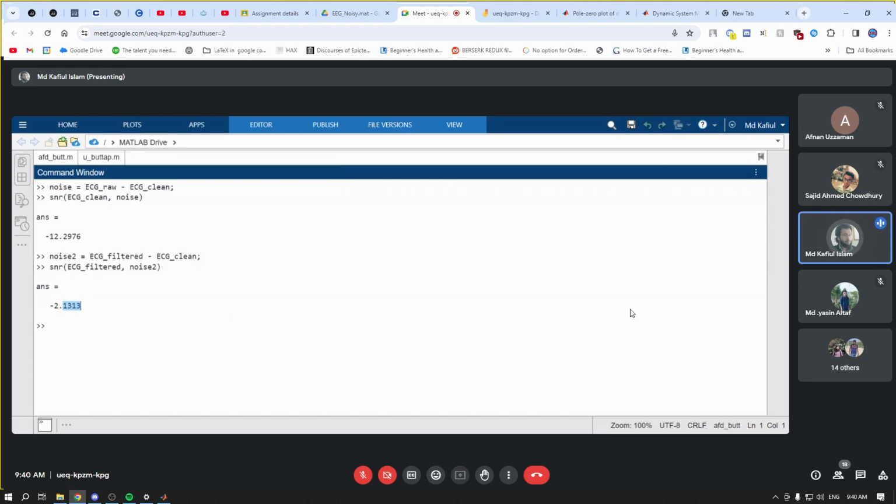So what does 10 dB mean, or what does 30 dB mean? That means the signal power divided by the noise power, and then the log of that, right? So why does it come out as negative decibels? Because your noise power is still higher than the signal power. That's why the log of a fraction is negative.